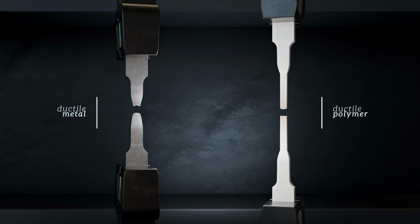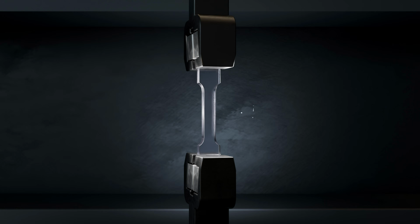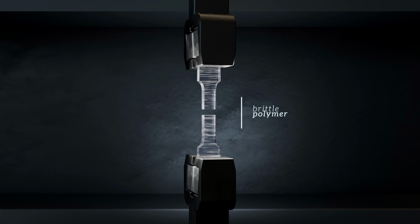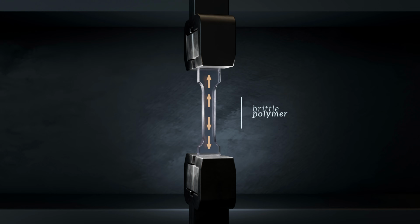Unlike ductile polymers, brittle polymers fail with very little plastic deformation. Instead of stretching, they fracture suddenly at low strains. A unique phenomenon associated with the failure of brittle polymers is crazing, where a network of fine, linear features form within the polymer just before fracture.